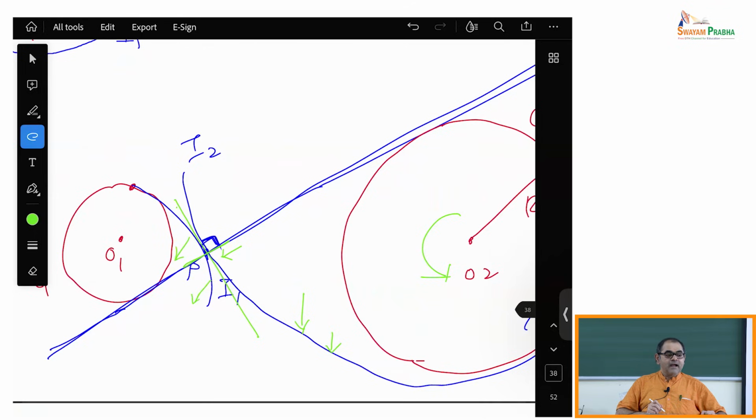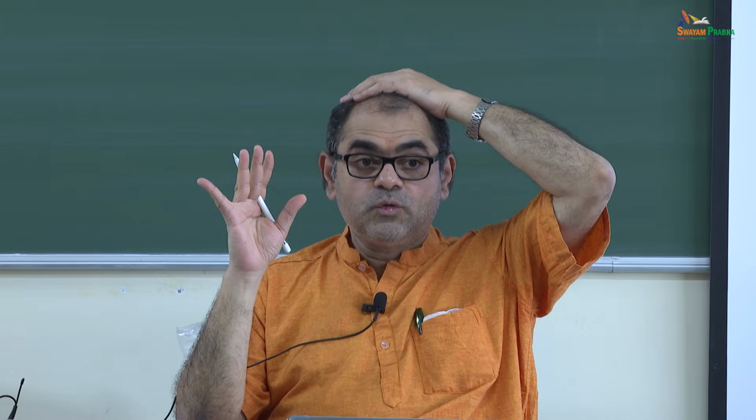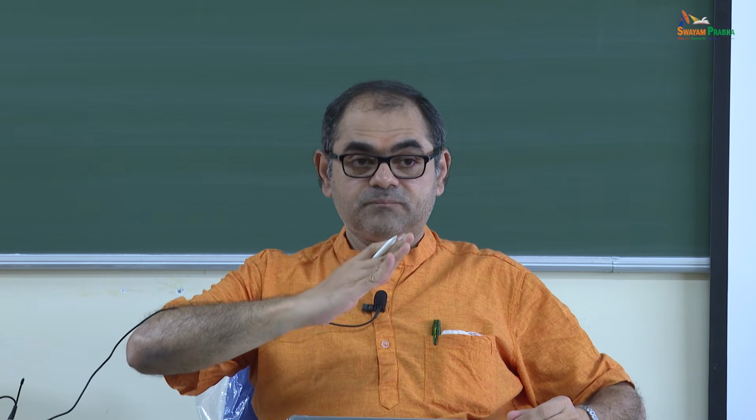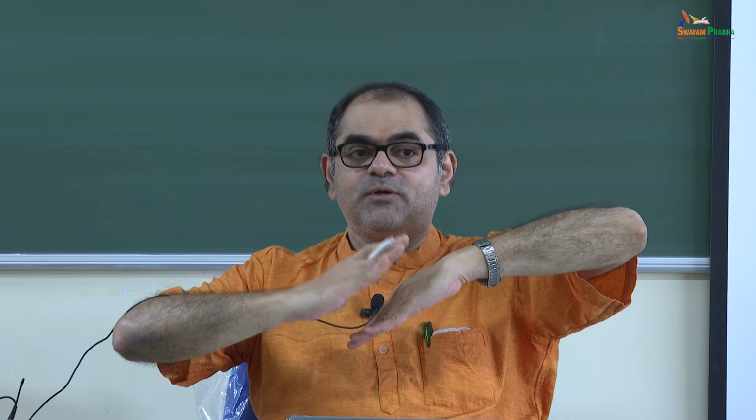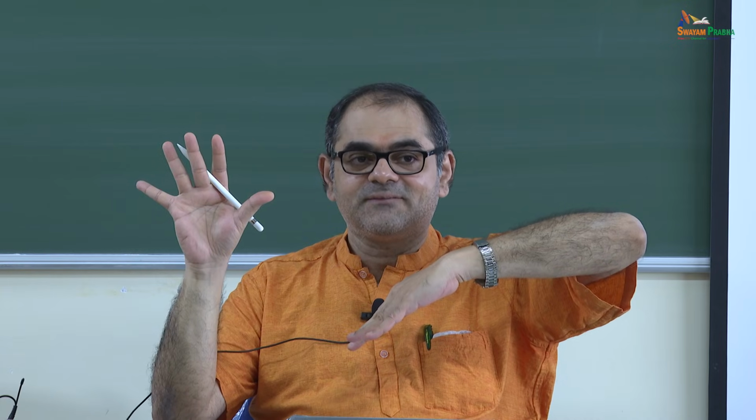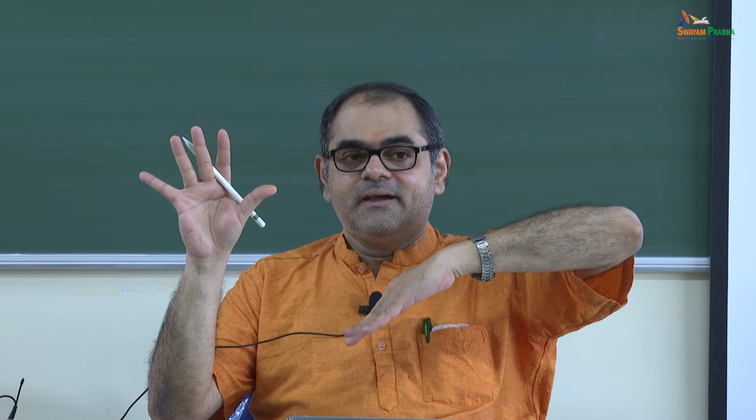Okay, and you can see that the point of contact will start moving upward. No. See, when you move this involute, it is like looking at a parallel involute. I mean, if you physically move it, after some time you will get a parallel involute if you consider the original curve. Okay, so there is some dynamics in this.